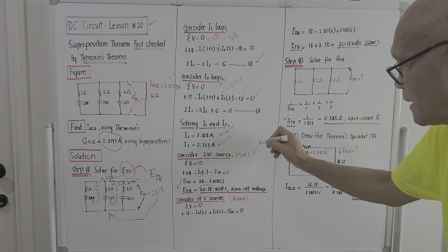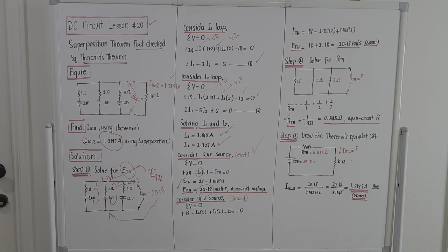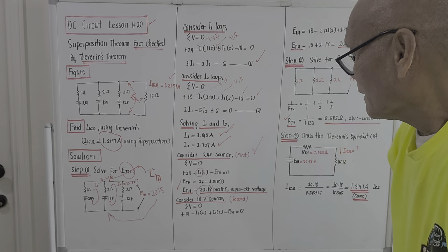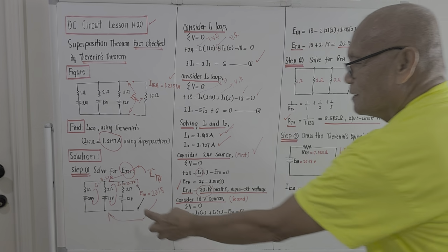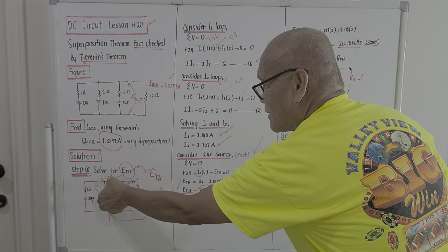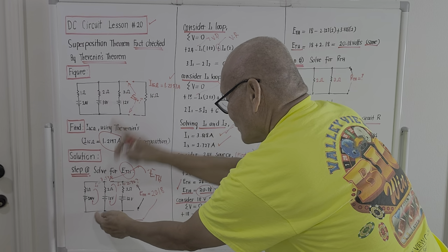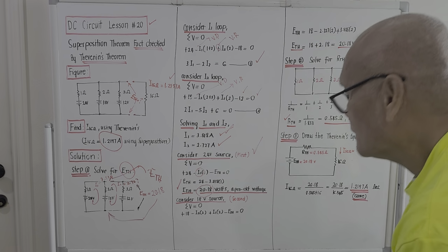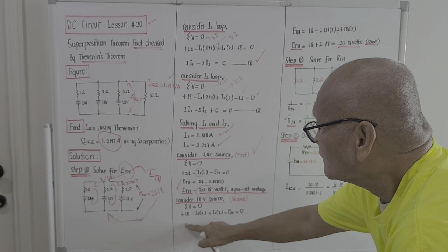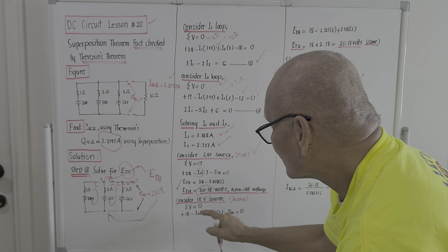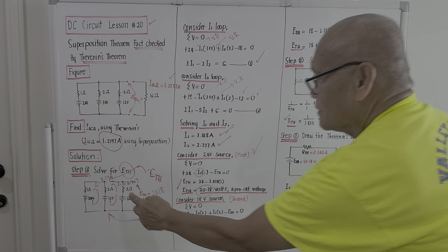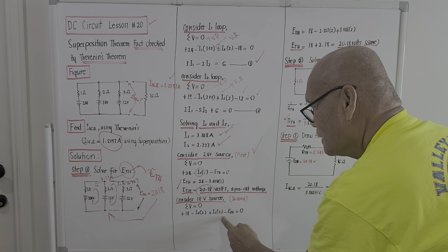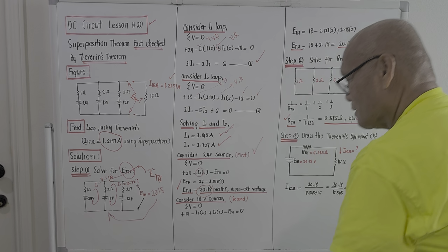And to check the validity of the open circuit voltage, I will check the summation of the voltages considering the second law. Okay, 18 minus the drop here minus VTH should be equal to 0. So actually, there are two. 18 minus I2 times 2, but this I1 here has an effect. It should be plus I1 multiplied by 2 minus VTH, and it should be equal to 0.